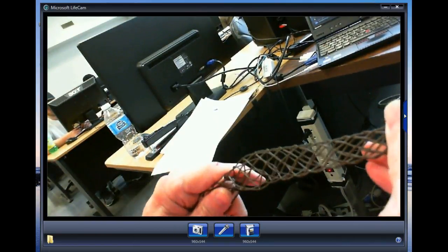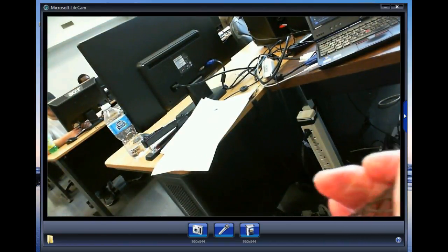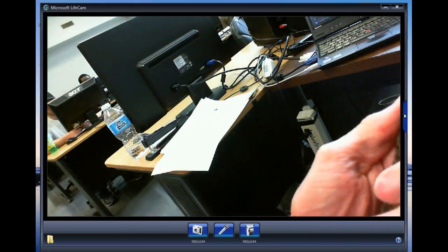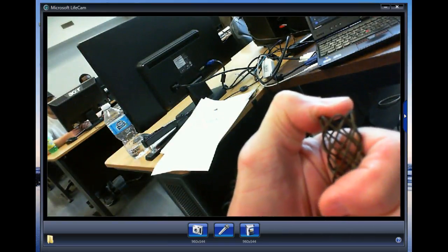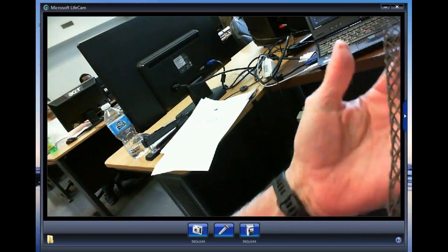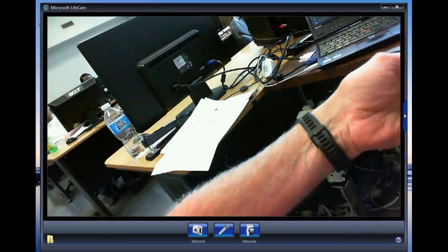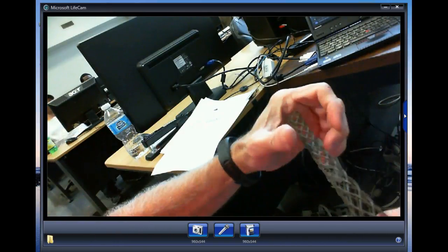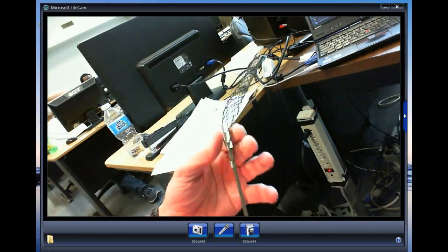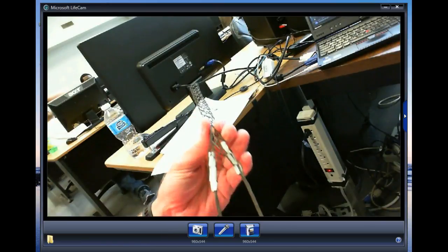This is the pulling grip, or the cleaning grip, that they were talking about. So notice it's got a wire mesh on it. And what you do is insert your cable, and push it in, and of course that makes it spread out, right? And then you insert your cable. And then you buy these for different gauge wires, and then when you pull it in, and then you try to pull it out, so don't just stick those fingers in it, because it'll grab onto it. It works just like what we used to have, Chinese finger traps.